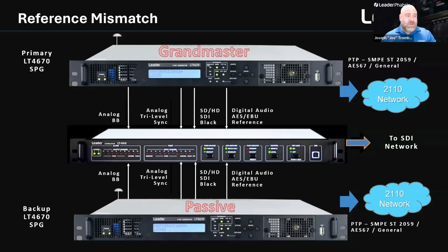The danger is thinking that primary and backup are enough. The actual issue is whether or not both remain phase coherent through a failover event. So you're not just protecting the packet flows, you're protecting cross-domain timing relationships.